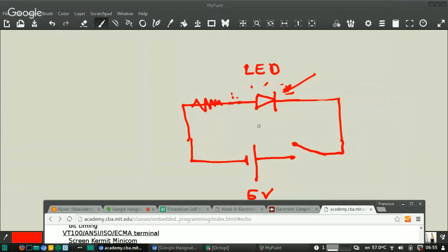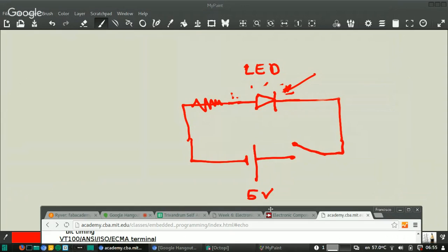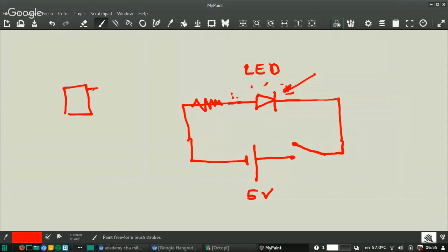If you have this simple circuit, do you need a microcontroller in there at all? Actually, we are not making this circuit. We are just using a microcontroller. It has many pins that you can use, and you are hooking here one resistor and one LED that goes to ground, and here you are attaching a button that also goes to ground.